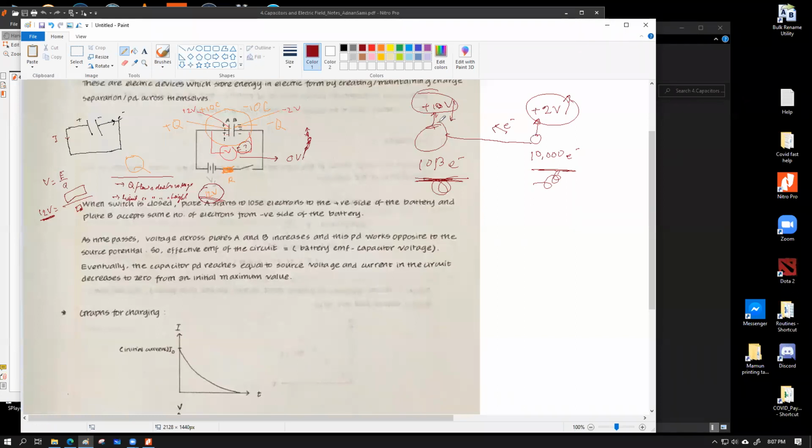let's say ultimately the voltage becomes fixed, so this one becomes plus 8 volt and this one also becomes plus 8 volt. I'm just assuming these two numbers, that this one is a large object, so even by absorbing a big number of electrons, its voltage is not going to change that much. That's a basic assumption. So whenever their voltages become equal, that's when the current flow will stop. So current flow is not dependent upon the amount or number of electrons available to an object. Charge flow happens due to the voltage difference.